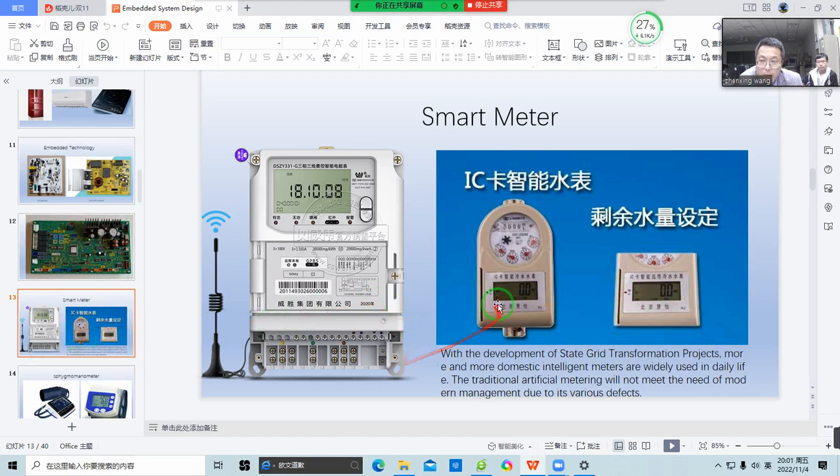So inside the microprocessor, they have a timer. After you insert the IC card, the timer becomes running. So your software should program the timer. How to program the timer? Make the timer run in interrupt mode. There are different kinds of running modes. Some are interrupt-based.